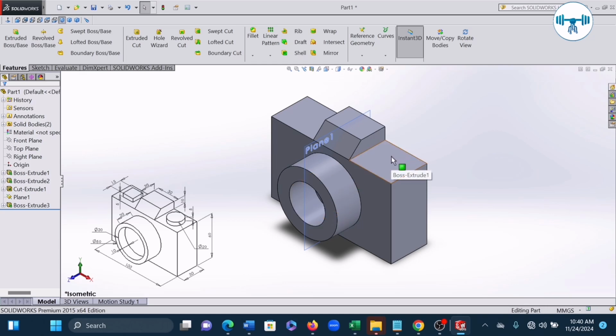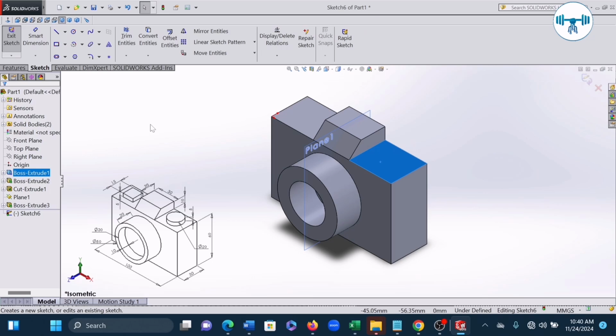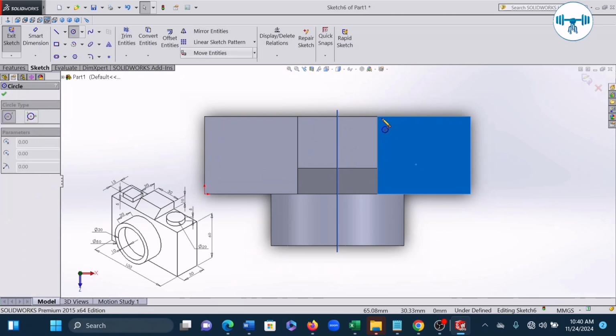So on this face, I'm going to click on this face and do what? Open up a sketch. Then I'm going to put it normal to again, then circle, and then I come and look for the center. Okay, so remember, I've not clicked yet. I'm just looking for the imaginary line that will give me the center. So I have this vertical imaginary line. Let's get the horizontal one. I have the horizontal imaginary line. So let's look for the intercept. This is this point. Good.